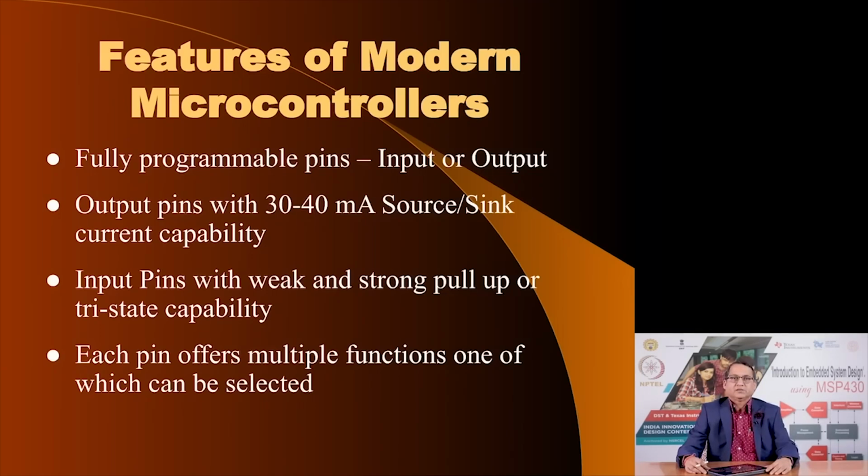Thankfully, that is not the case. All the general purpose pins that are available, apart from the specialized function pins such as power supply, and there may be other specialized function pins, the rest of the pins are programmable, and by writing an appropriate program, the user can decide which of the pins will function as inputs and which of the pins will function as outputs.